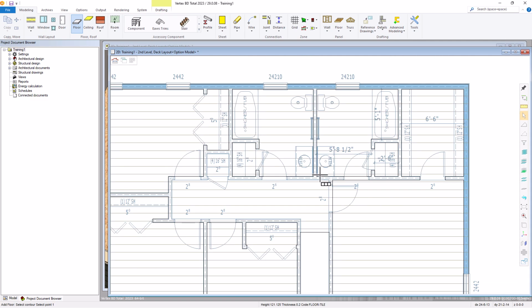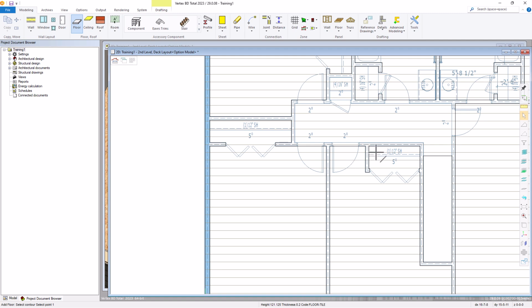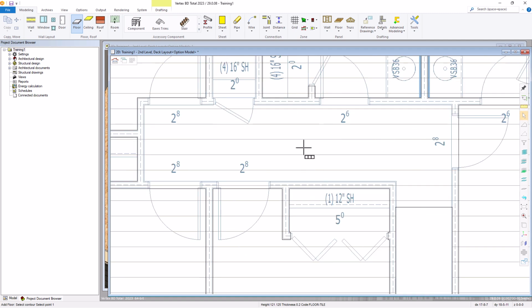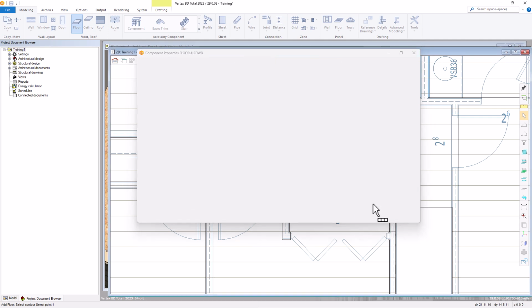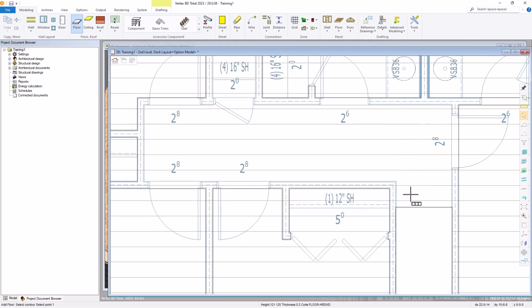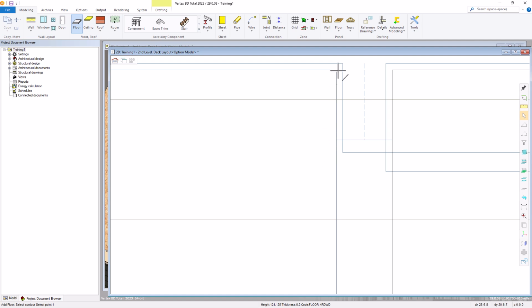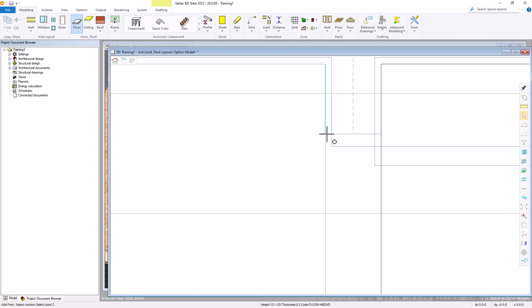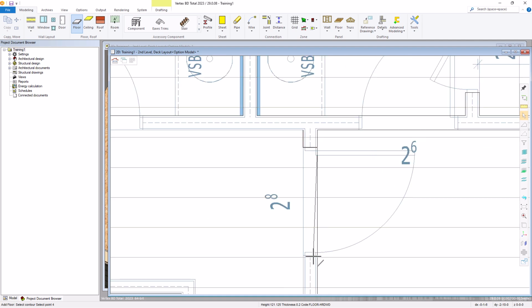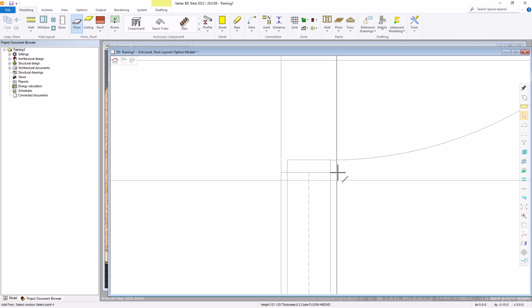Now let's add the hardwood floor in the hall area. So zoom in, right click, edit parameters, and we'll select floor finish hardwood. And select OK. Let's start with this corner up here. Let's go into the drywall, and we'll go into the doorways along the edge here because that's where we ended the carpet. Go to this corner, that corner.